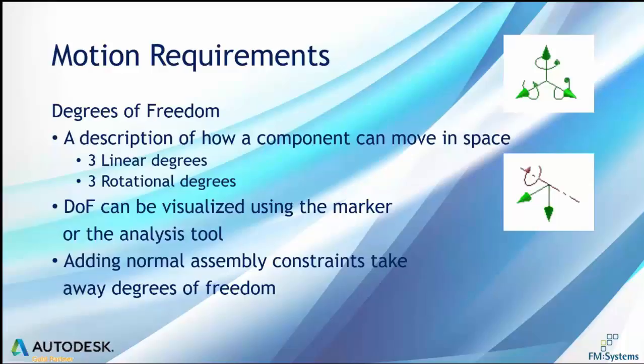So if I put a mate constraint together, it allows me to limit a translational change, and at certain points, it can even change a rotational degree of freedom as well, depending on what I mate or constrain together. Okay, we'll look at those as we go through the modeling to see how we can use that within the motion side of the assemblies.